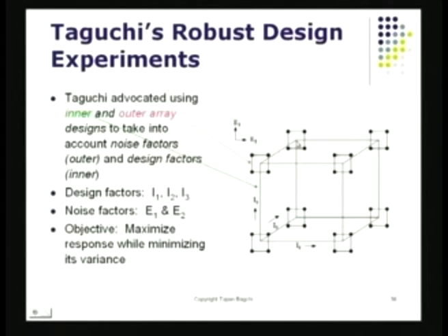So here what I'm doing is, I've got a product, I've got a prototype, and I'm going to be shaking it with the environmental factors. If I've got a product in my hand, I'd try to impact it using environmental factors, which in this case could be a physical force, it could also be temperature, it could be dropping it, and so on and so forth. Even the quality of the components could be considered noise factors.